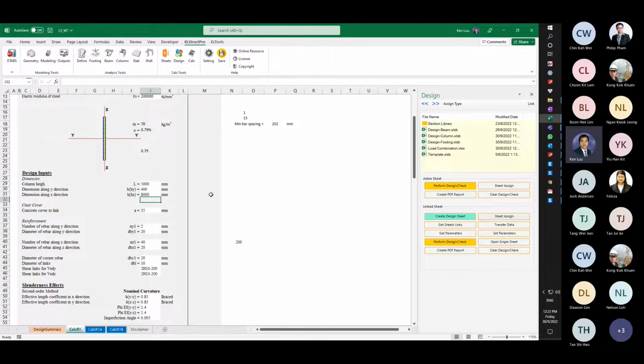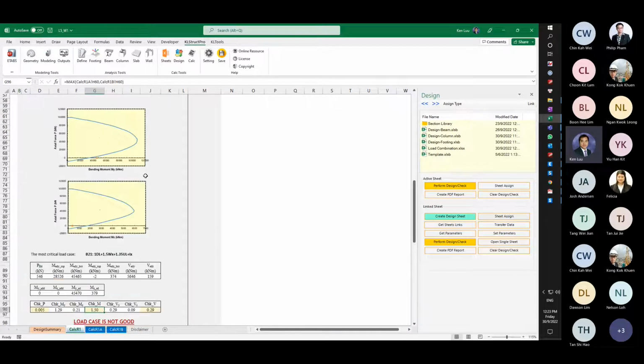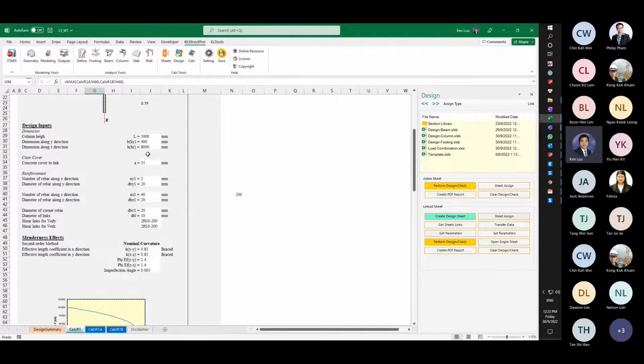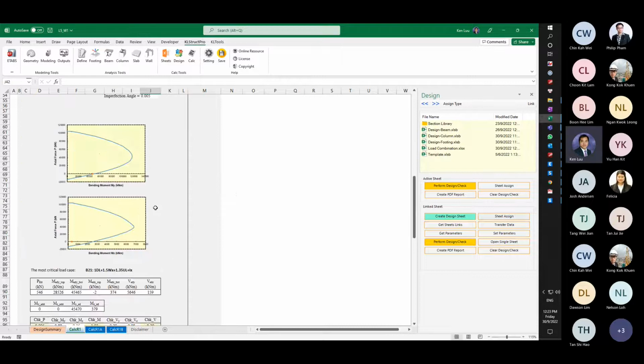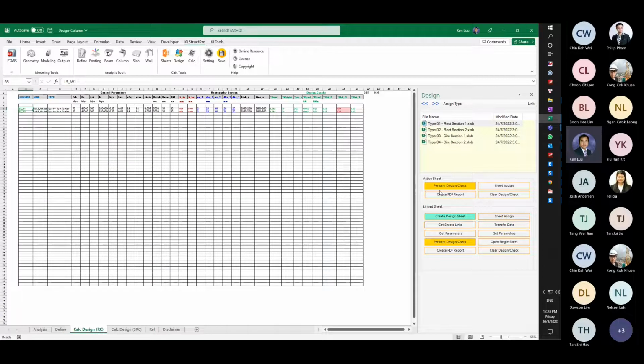accordingly. So there's two ways to improve the design. One, you see this one not passing, right? So something the M is not satisfied. Either you can increase the rebar. You can increase the rebar, and then you check here, and then you save, and then you go back to the summary table, and then you get the parameters.